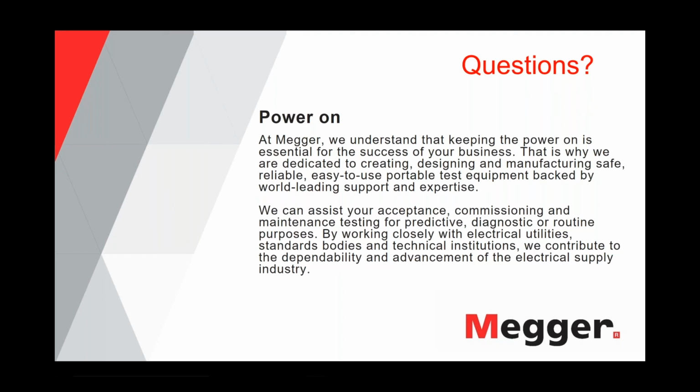So the only thing you can do there is really clean the terminations and wipe them dry. Now, if you have water in the conduit, that's a different issue. That comes right back to measuring water ingress or moisture ingress into the cable insulation. Now you measure it in the insulation. That means that water is really in the insulation, and it's a bad thing. When it's on the termination, you typically have a way to circumvent or mitigate it.